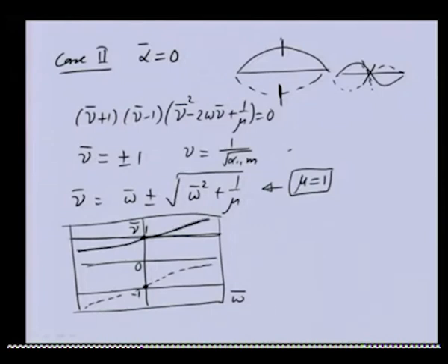So you can see that at one particular omega, apart from the 0 spin speed, if we draw a vertical line, we get 4 intercepts: 1, 2, 3, 4. But there are 4 whirl frequencies, and you can see that two of them are the same, so they represent the same one.